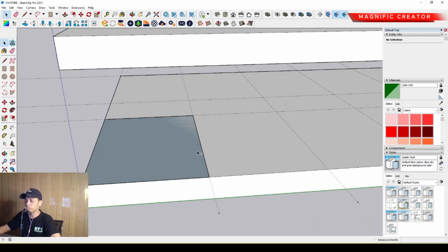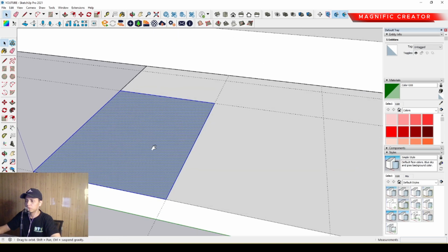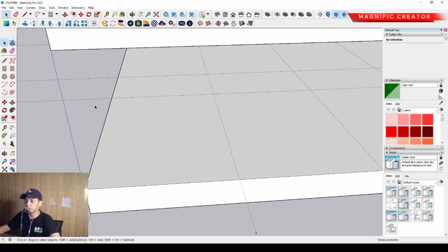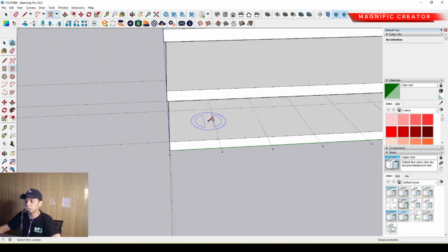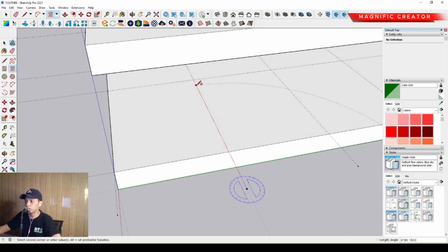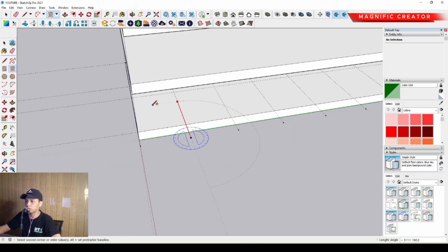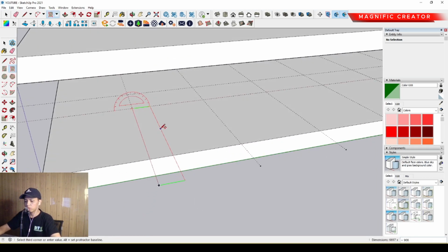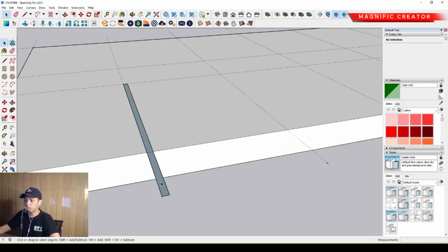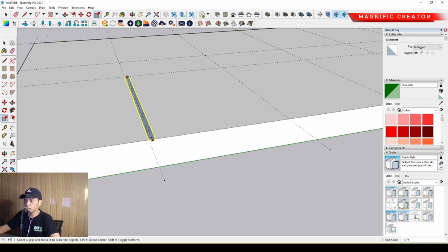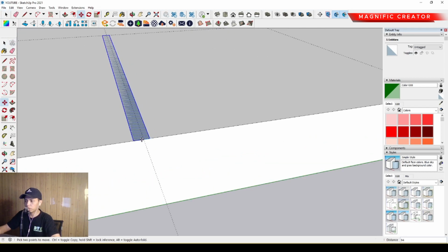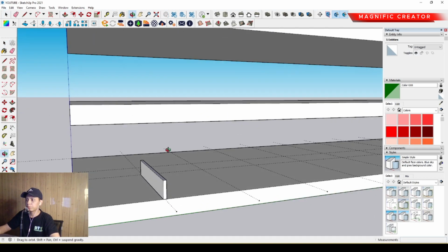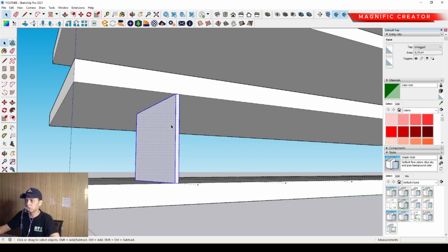Okay, it is about the room of a residential unit. After that we can make the wall. We can make the wall from here. We can set it around 150 millimeter, and we can scale it. Then we can move it to the middle. Then we can push it up until the top position of the slab.